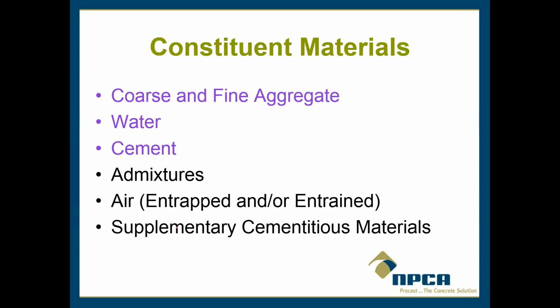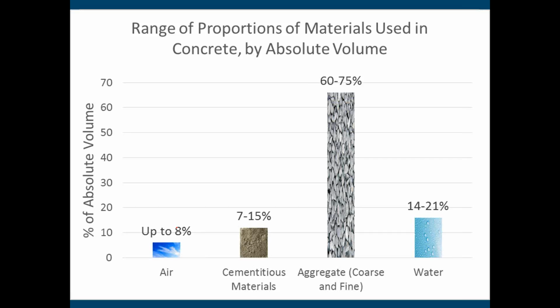And why do we exceed that magic number that we were just talking about? Is that what you were referring to? Yeah, why would you ever exceed a perfect water-cement ratio? I think we just answered that. Water for convenience, water added in order to work the concrete, in order to get it around reinforcing, etc. Yeah, good question.